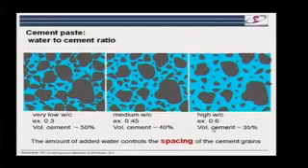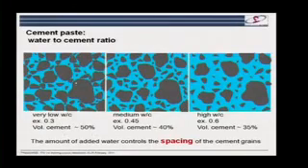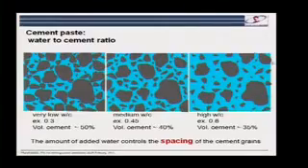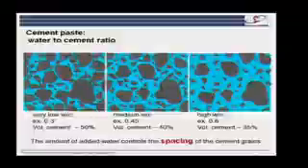And here I've shown the equivalent volumes. And if you, just in your head, double those volumes, you can see that at this end, we get to a point where we can almost fill up all the space. So we can almost have no porosity at all. Whereas at this side, we're inevitably going to end up with a lot of space left over, which is going to lower the quality of the concrete.